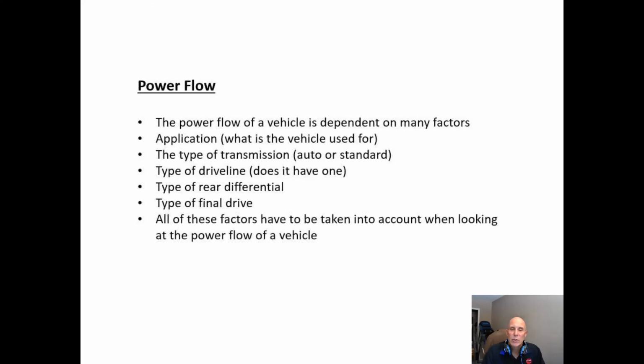What type of transmission? Is it automatic or standard? What is the gear ratio set up in the transmission? Again, what was the truck spec'd out for? Type of driveline does it have? Type of rear differential? Type of final drive? Does it have outboard planetaries on it? All of these factors have to be taken into account when looking at the power flow of a vehicle. So that's the basics of power flow.